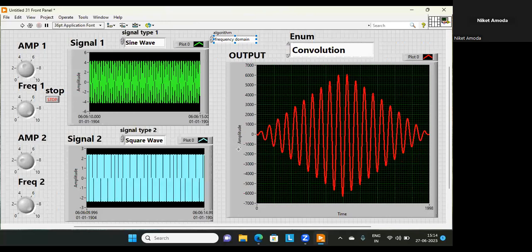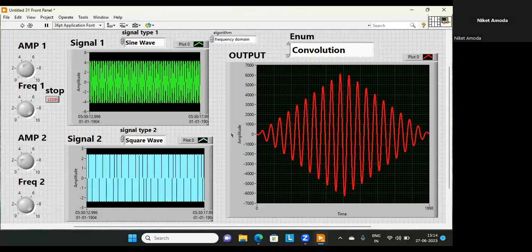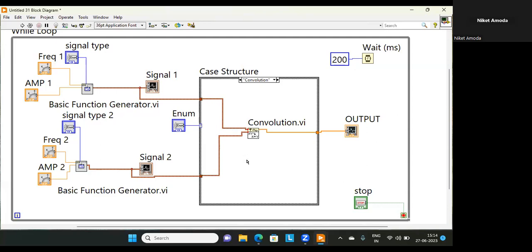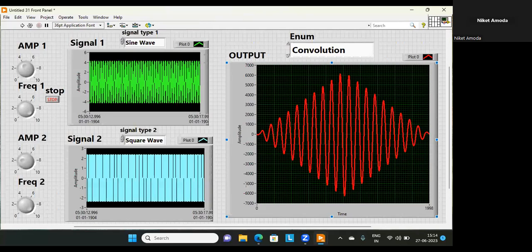There's one question. Yes. How to interface this LabVIEW output with the plant? Sir, basically, LabVIEW can be interfaced with many data acquisition devices. DAQ devices are NI products, as well as products of any third party. For example, if you have multiple sensors, you create a sensor network of flow, pressure, temperature. You can give it to any input port of a DAQ, and you can do a digital or analog reading of that data on the LabVIEW front panel.